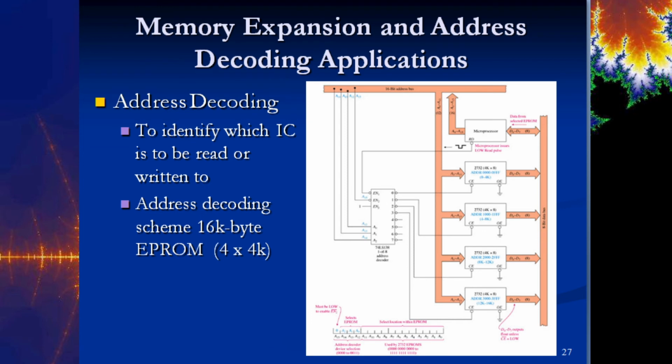So if you've got more than one of these IC chips in your circuit, then you're going to have to do some more decoding, right? So we keep talking about decoding, but think about it. It's really the only way that we can communicate between these different chips, because we can't put the number 15 on a line. We can only put ones and zeros. So we're constantly taking a value and converting it into a single output through all of this decoding. Okay, so here we go.